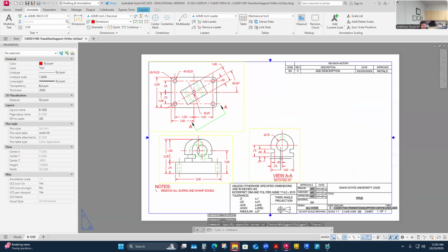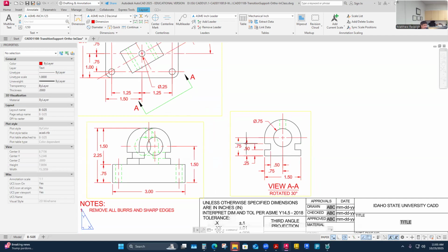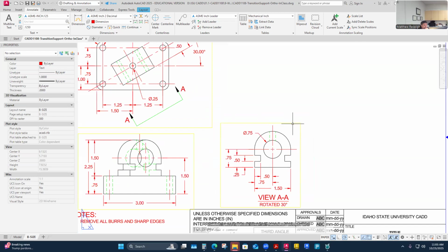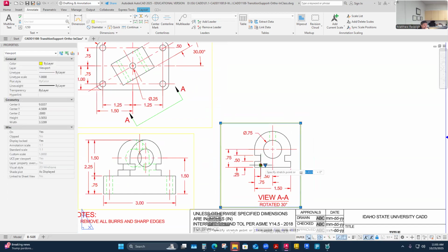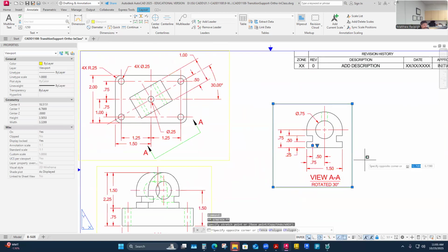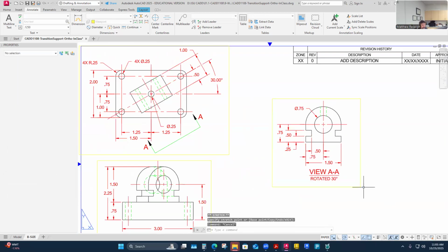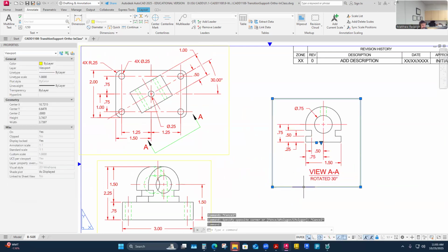So if my top view doesn't fit here, I'm going to have to maybe consider scaling it down, which will affect everything. It'll affect my spacing and stuff a little bit, so I'm going to try not to have to do that. But there might be a reason that I don't need to orthographically align this, technically. This is a dislocated view, so I could break this rule right now. I'm not going to worry about that orthographic alignment because technically I'm off this anyway. In fact, it's better if I don't connect those orthographically, so that I keep the true nature of it being a rotated or removed view.